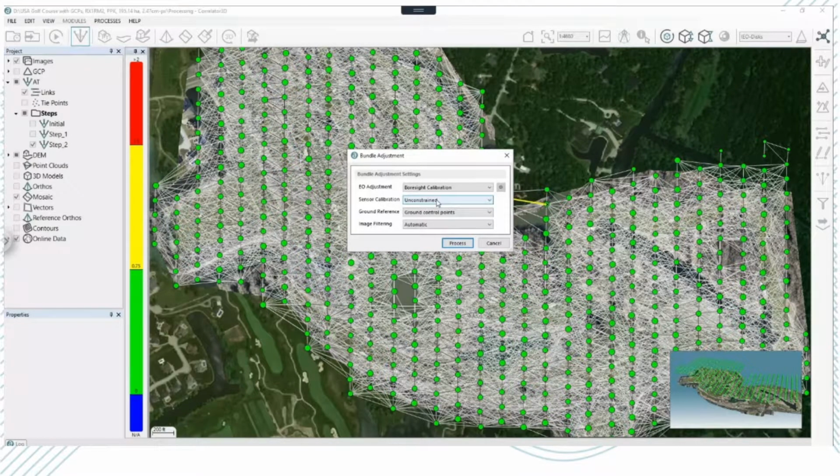For LiDAR to be any good, all the corrections have to be made on that LiDAR, forward and backward processing and all of that. So honestly, if you think of it this way, when LiDAR is captured, the IMU and airborne GPS are capturing the information, and you post-process that data. I could explain it this way: it's like a pool noodle. It's this big. Your error is that big.